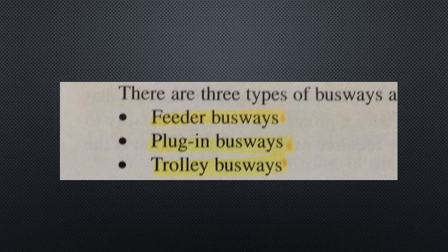Busways. Busways are sheet metal enclosures into which conductors are installed at factory. These conductors, which are actually copper or aluminum busbars, are supported by insulating material. Busways commonly come up to 10-foot sections and are bolted together when installed horizontally. Busways require supports every 5 foot unless otherwise designated. Busway systems are often used in commercial buildings as their primary wiring method.